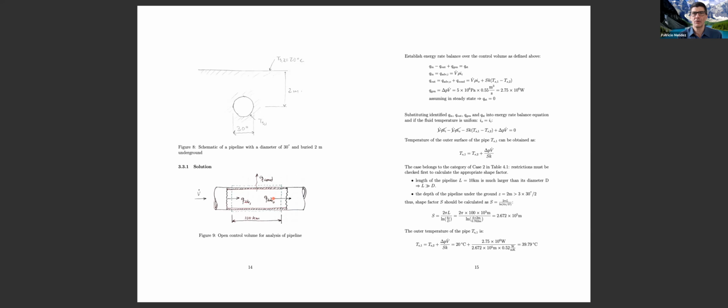So this is part of what goes on Monday, Yanni's part. I imagine that the notes on differential control volumes are quite abstract, but if you take a look there, you'll see that we discussed the Peclet number. And the Peclet number is the ratio of advection to conduction.